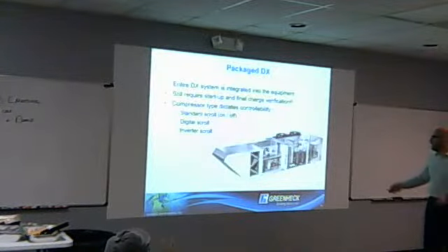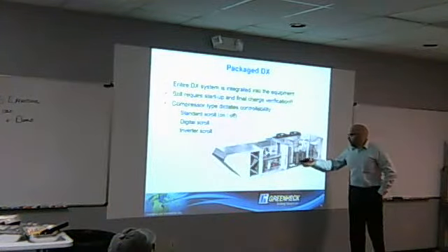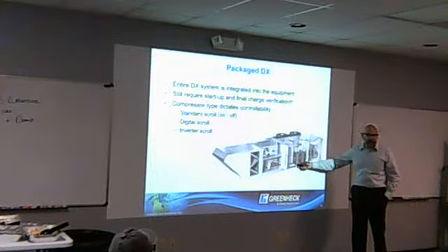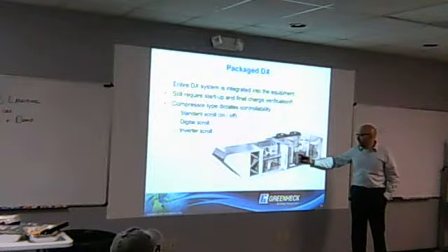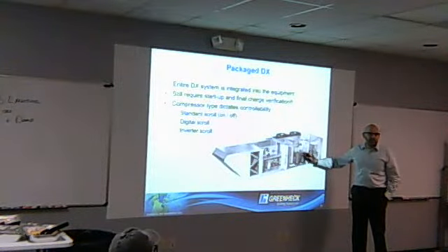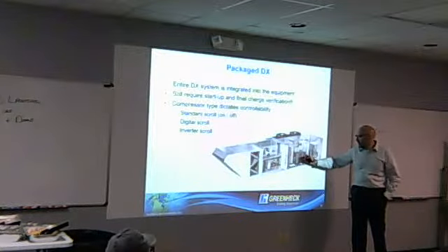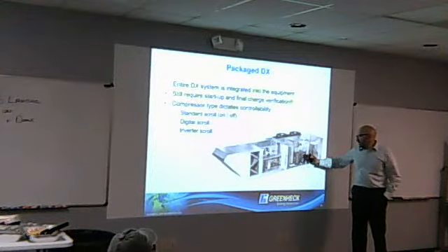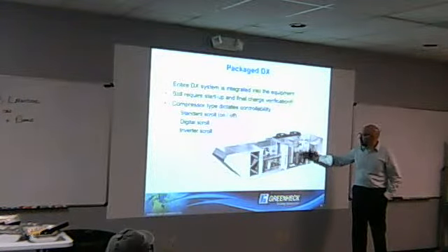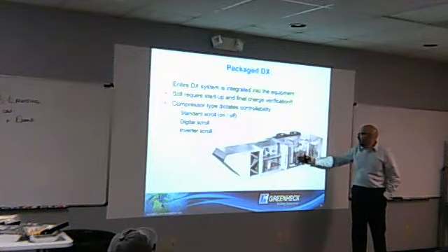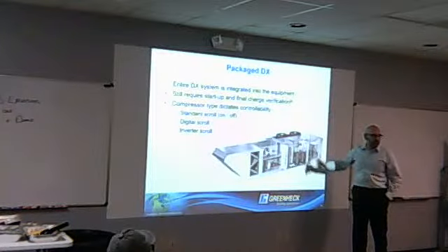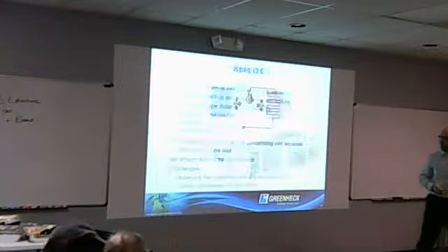And when you have two compressors, the second will be full speed and this will be modulated. Because if you're going to bring this up to full speed, this one needs to run at full speed. You don't need two modulating compressors. So you're going to run both full speed and then modulate this one down. If your capacity was 100% here, if this was a 10-ton unit, you got 5 and 5, you got 5, and then this you only need 6. You bring this one back up to 1, as opposed to having 2 and 2.